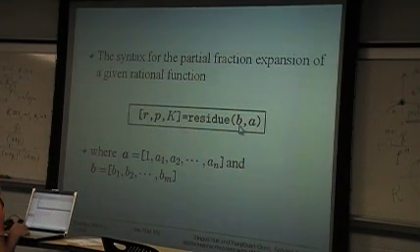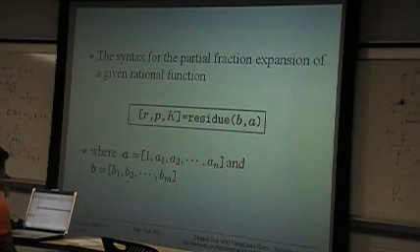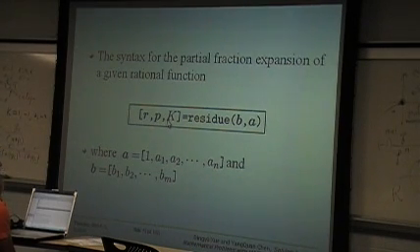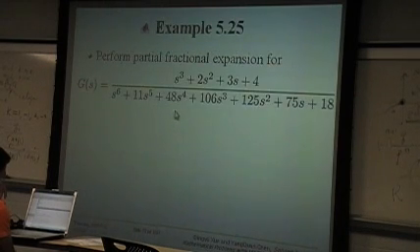In the function call, we have b and a, where b is the numerator polynomial, a coefficient vector, and a is the denominator polynomial, also a coefficient vector. Then we can call the residue function and find the r vector, p vector, and residue k. And I will demonstrate this function by an example.